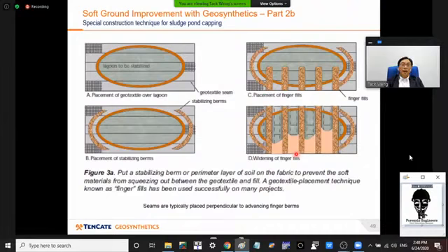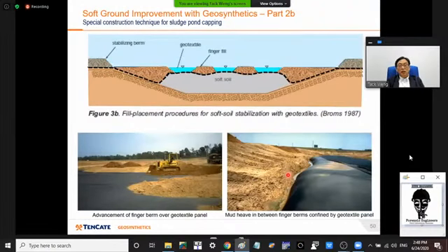And here the whole idea is you want to limit the mud heaving that will happen when you put fill on top. And you can very easily imagine that if you don't have the fabric, then it will be all messed up.